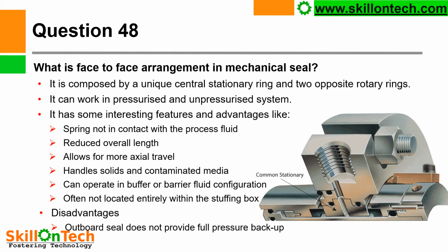What is face-to-face arrangement in mechanical seal? You can see a picture where face-to-face arrangement of a mechanical seal is shown. You can see here that there are two common stationary seal rings provided at the center, and these are the rotary units provided outside. It is composed by a unique central stationary ring and two opposite rotary rings. It can work in pressurized and unpressurized systems.